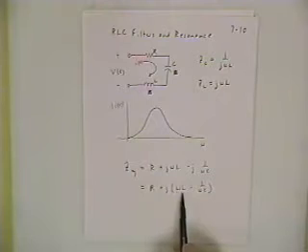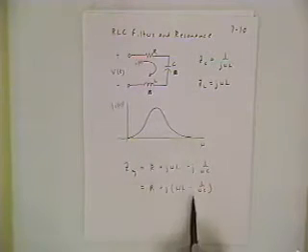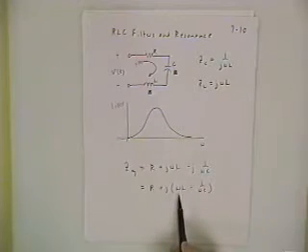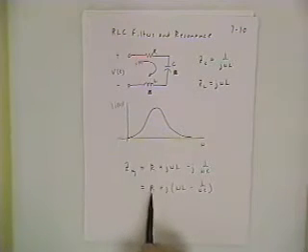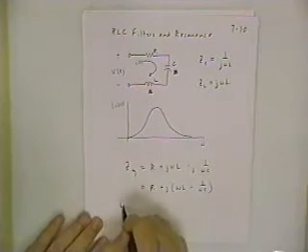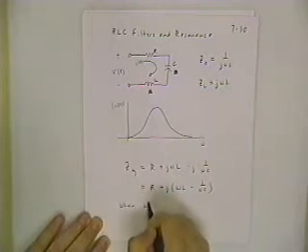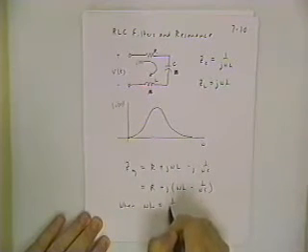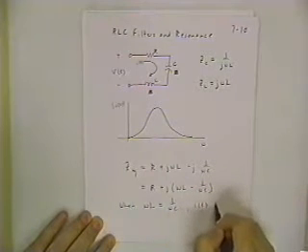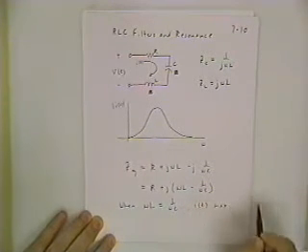There's some frequency in the middle of these two extremes, some frequency where this imaginary part just drops out completely. The impedance becomes purely resistive, and the current is a maximum. And that happens when omega L equals 1 over omega C. I of t is going to be maximized.